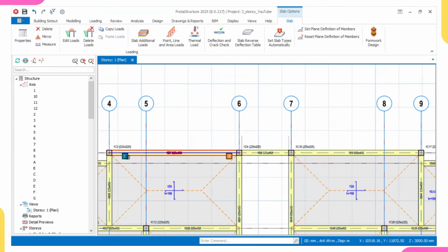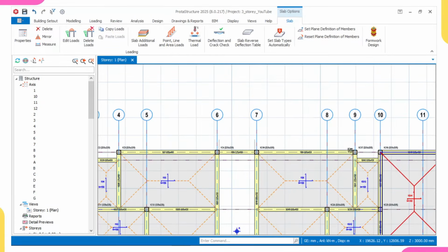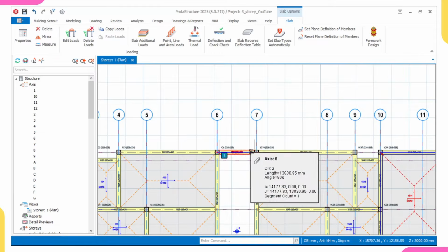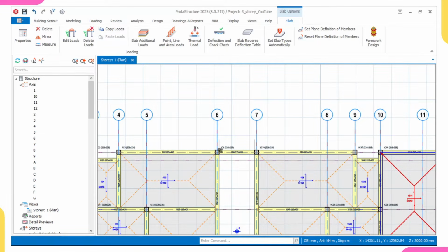So remember, if you are to hinge the beam, we are going to hinge here and hinge here. We are not hinging here because the summation of moment here is not equal to 0. We are also not hinging here because this is a continuous beam. So the moment here is not 0. Here we'll be having something like this. It will come down and go up again, come down. We're having hogging moment here, hogging moment here.